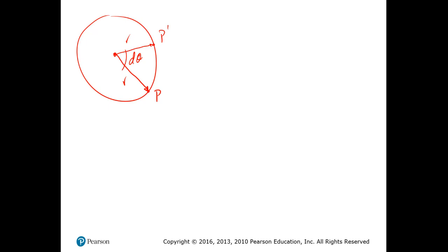All right, let's study what we just learned. We have a rigid body, and this is the center of rotation. We're studying how this P moves from P prime. It's not giving us a P prime, but anyways, it's just the location of P after t equals something. The distance from this center to P is what we call r, and the distance from here to here is also r. We are studying how these particles move from this point to that point, and we're going to call that d theta. For us, it will be easier to find the s, which is what we're studying here, how it moves.